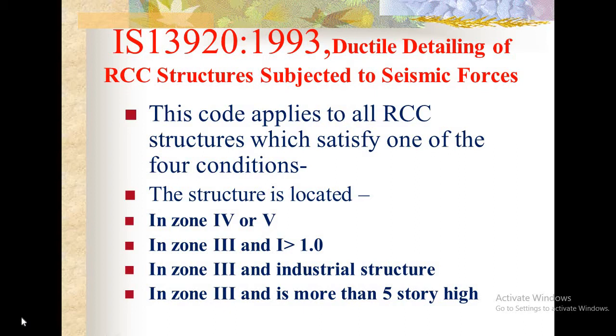The ductility increases linearly with increase of shear strength carried by the concrete for small values of axial compressive stress. With the increase of ultimate strain of concrete, the ductility factor is increased. Hence, confined concrete is more ductile. Ductility increases with increase in concrete strength, but an increase in yield strength of steel decreases ductility.